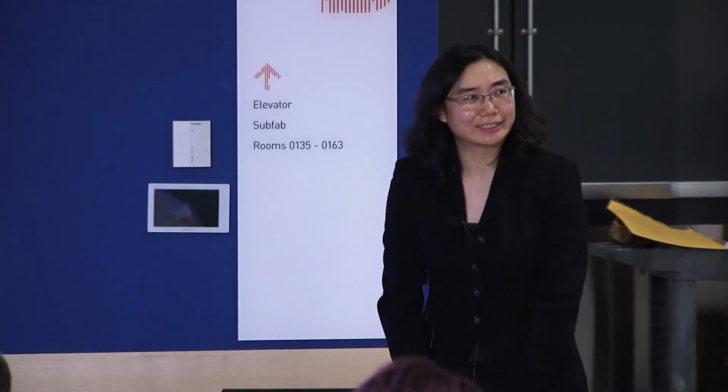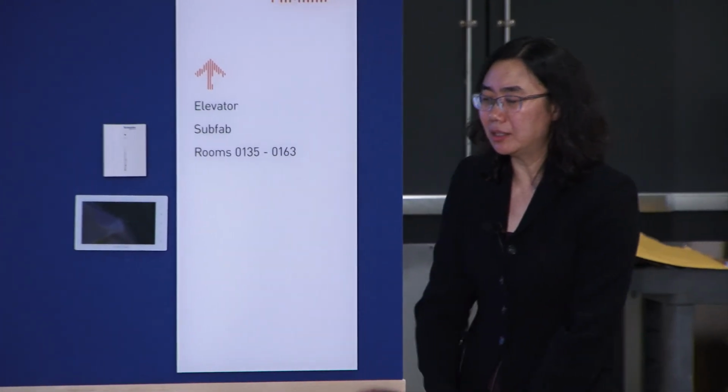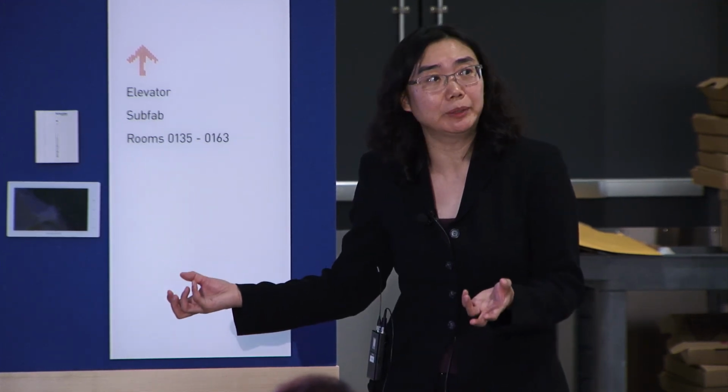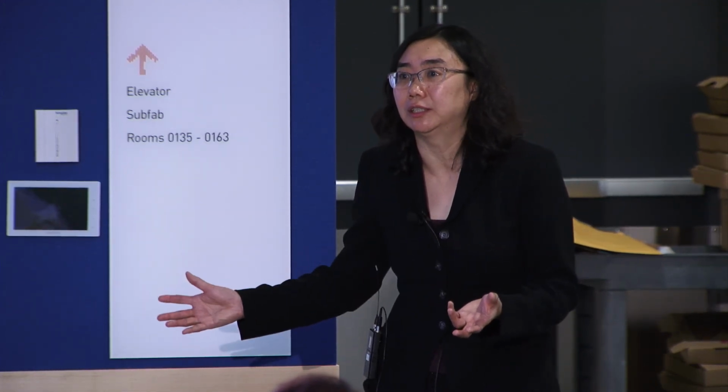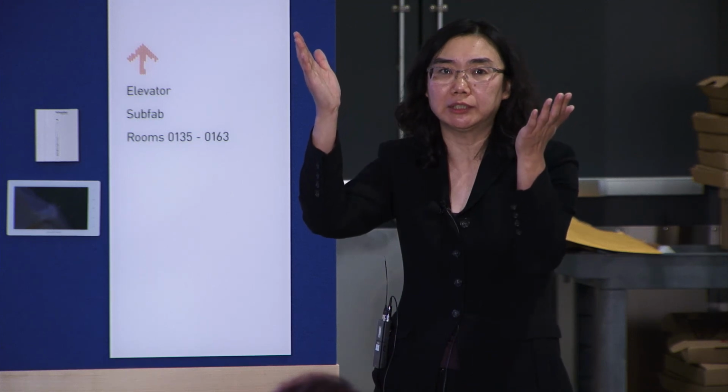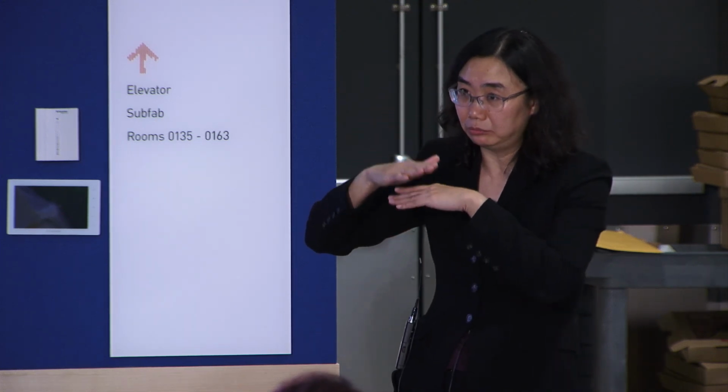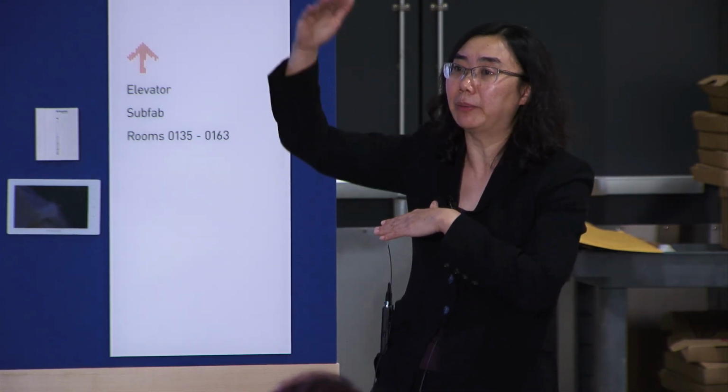I hope I get it correctly. So what we have seen is in the industry, we do a lot of research work. The advantage I think we have is we know exactly what problem to target, right? For the academia people, sometimes it's not totally clear. For example, everybody pushes for the highest TMR. You can show 600, but when you thicken up the MgO, the resistance goes up, the TMR goes up.